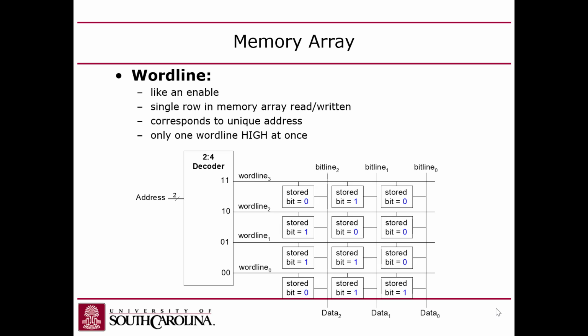So the word lines then are just connected to a decoder. So the memory address goes into a decoder, and then that address, which is a binary value, essentially gets converted into a one-hot, or some people call it a unary value, where you have a bunch of bits that come out and only one of them is hot, only one of them is 1, that represents one of the physical word lines in there.